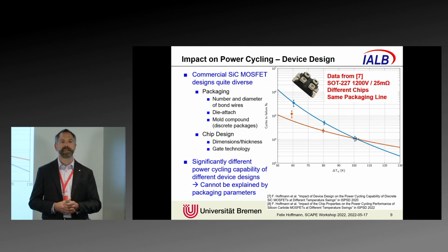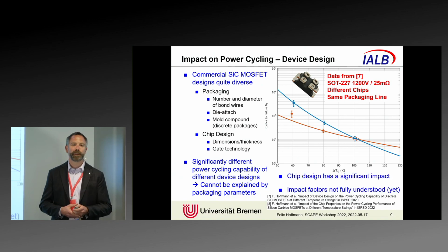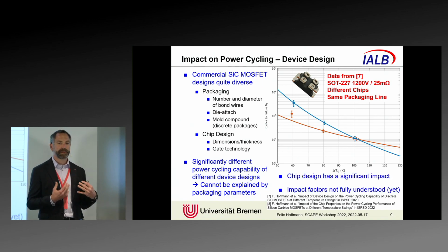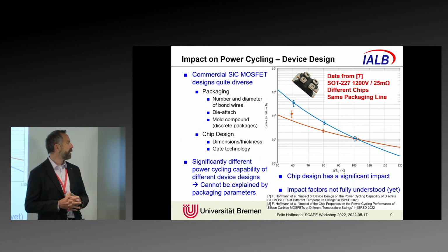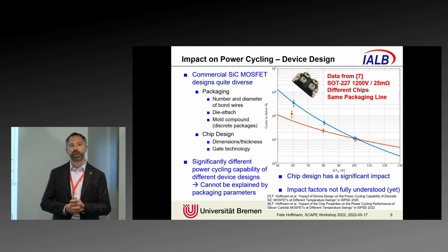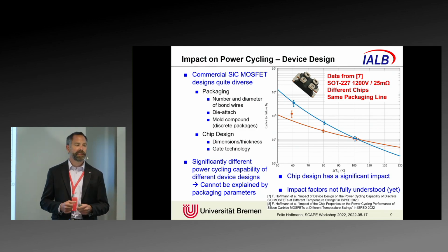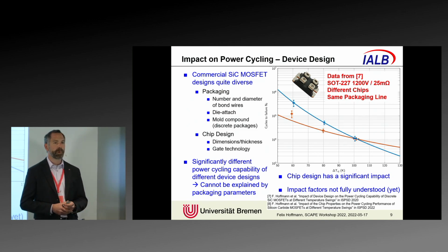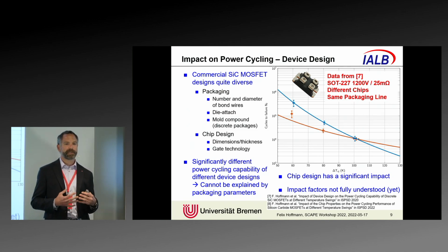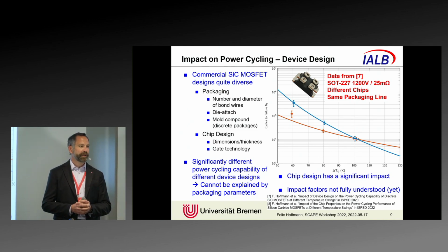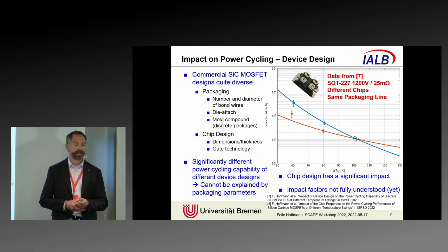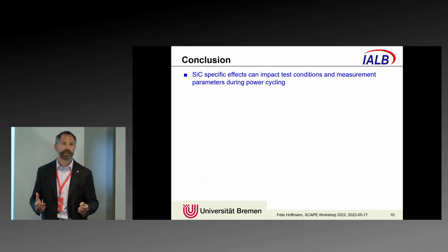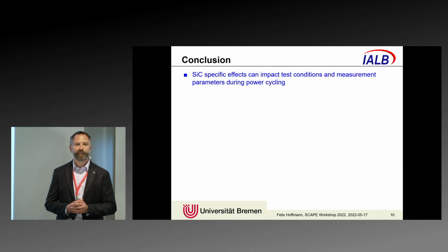However, those parameters are usually not considered in lifetime models. Since those are not fully understood, there is, of course, further work necessary to investigate this. But in any case, if a lifetime model is applied for silicon carbide MOSFETs, it needs to be made sure that the model actually works. This cannot be done by just simply performing power cycling at a single temperature swing, but multiple temperature swings are necessary. So, all right, let me conclude my talk here.